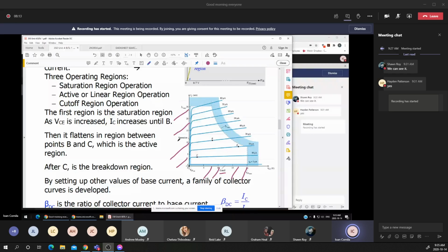At this point, we have to define the conditions to place the transistor in saturation, the cutoff, and the middle point or center area of the graph. You notice that on the y-axis is the IC, usually given in milliamps, and on the x-axis is the VCE, or the collector-emitter voltage.